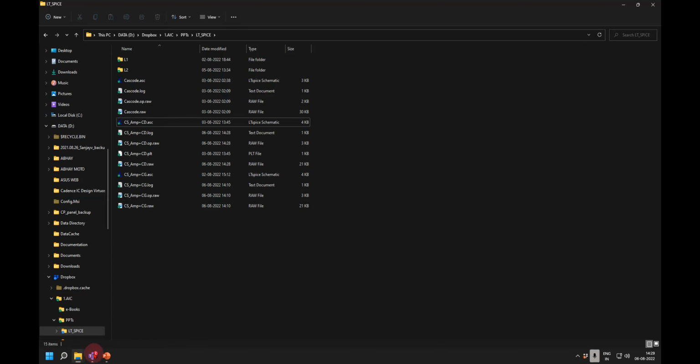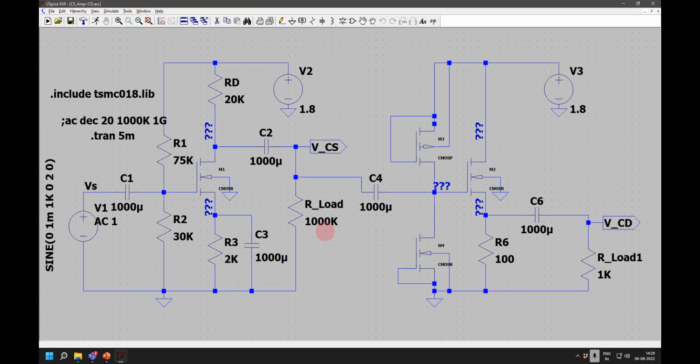Sir, why are M3 and M4 required? Which here? Yeah, these, the top PMOS and bottom. See, I can put 2 resistances there. I had to get the operating point out here, right? Both are off, right? Why do we need both? I have just inserted this to tell you that I can use MOSFETs also as resistance, mega ohms resistance in off condition.